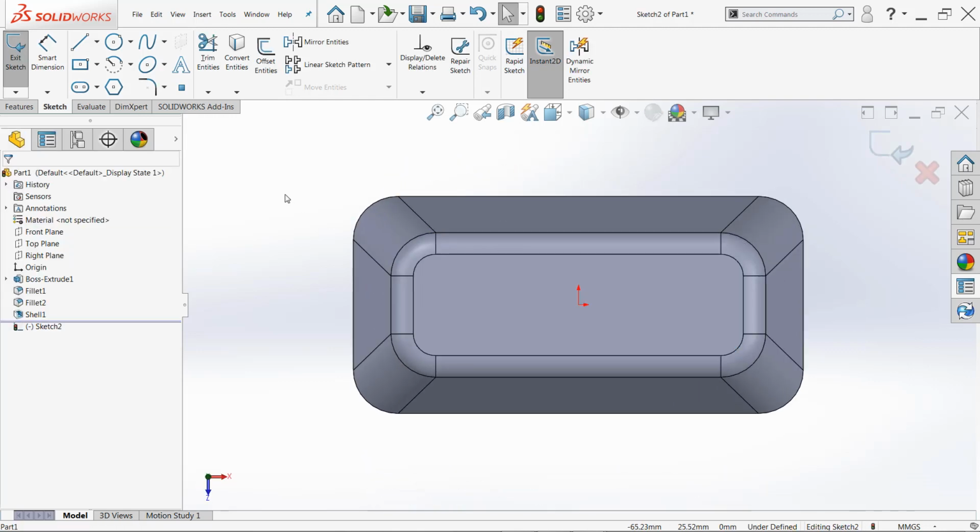You'll see that because of my system options, I'm rotated automatically normal to this sketch orientation, and then we can go ahead and begin creating our sketch. Now, first thing that you want to do, if you're using a revolved feature, whether it be a boss or a cut, you probably want something to revolve around. I'm going to use a center line for this.